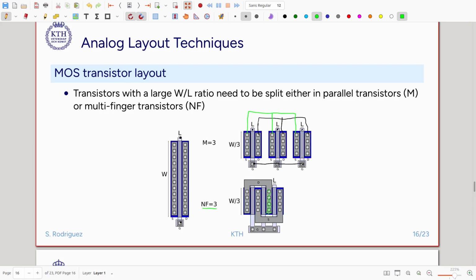This overlapping drain here, and then I will be overlapping the source of two transistors here. So I can reuse the same area as the source or drain for two transistors. When I do it like this, then what I will be changing is only the number of fingers in the transistor. So the transistors have the same dimensions, but it is more compact, easy to draw, and has low resistivity.